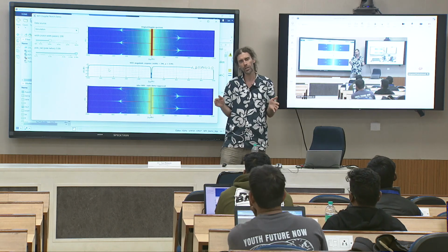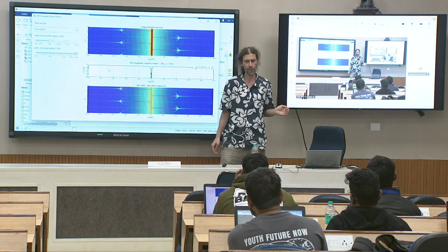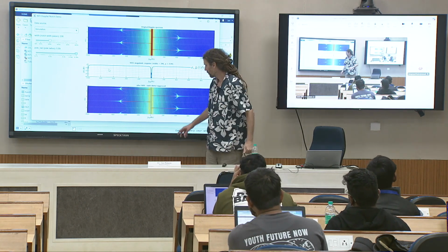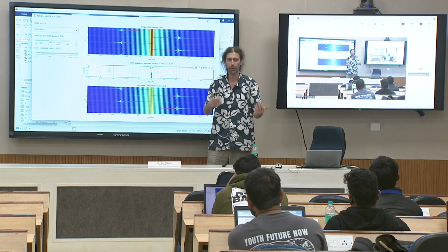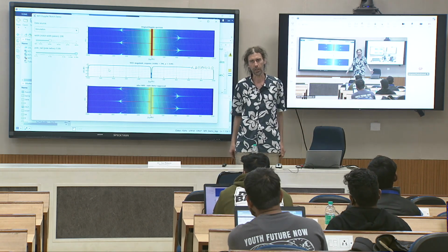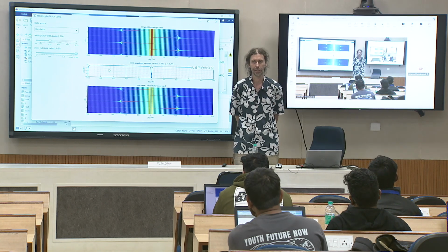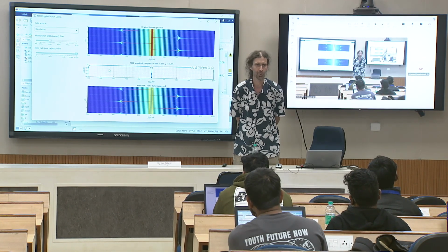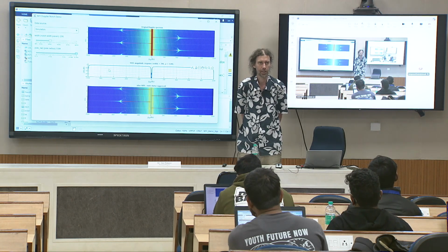And now you need to tweak it to your application, because of course if something has very low speed, then your target will be somewhere around there, and it is just a controlling mechanism for the MTI filter. What you consider still a static object and what you consider not a static object is up to you, like a radar engineer. So it is about just designing the filter.